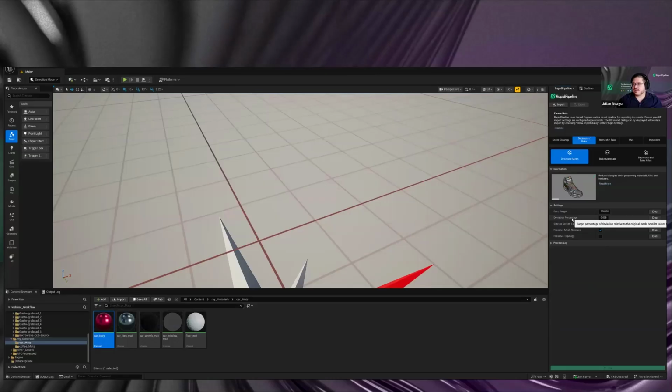So it's similar to the tessellation deviation, in that it just looks at the original surface and then computes the maximum allowed downscaling on the edge collapses on the decimation compared to that value you dial in. Right now it's in percentage, so it's always relative. Doesn't matter what unit you have or what size the model is. It's always relative to the allowed error. 0.005, for example, is a very small allowed error.